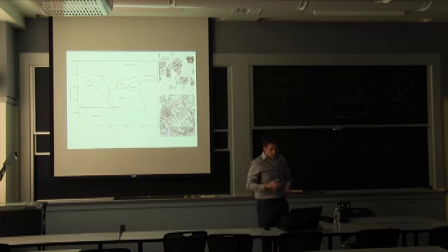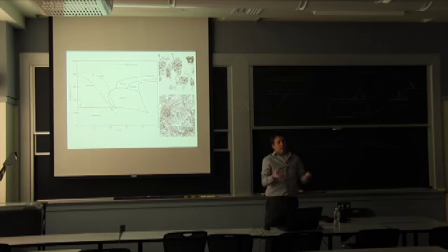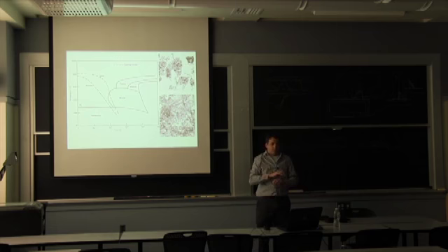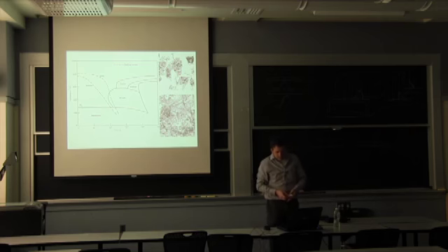So if you manage to quench the whole part before you reach the bainite tip here, and then you reheat it at a constant temperature, you get the opportunity to get properties that are about the same everywhere. And it's an advantage that a lot of people will take advantage of. It allows you to get both strength and ductility when you're in kind of a bainite regime.